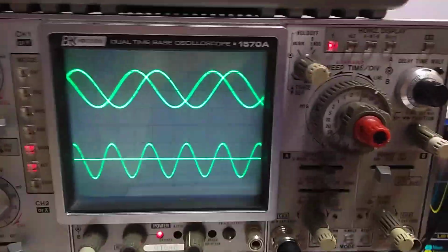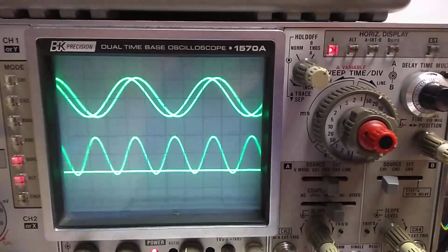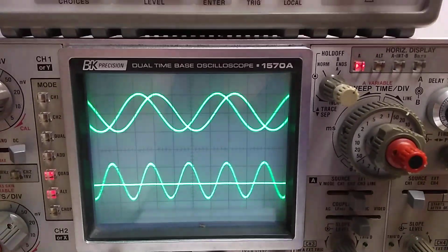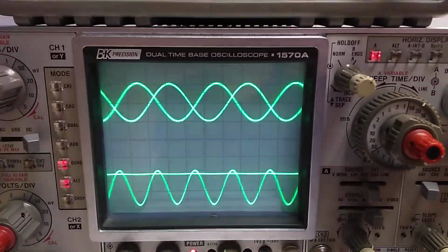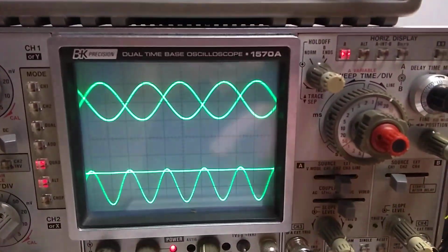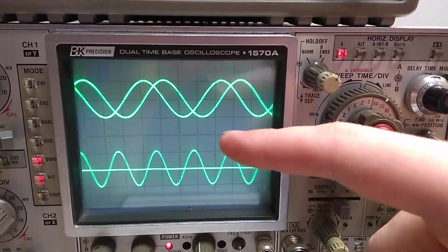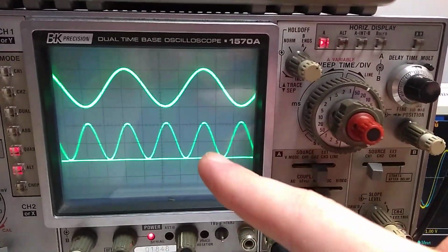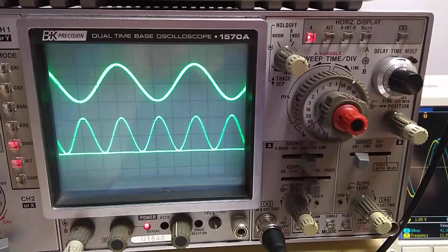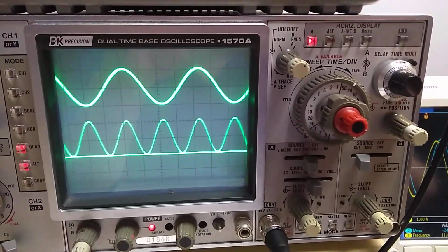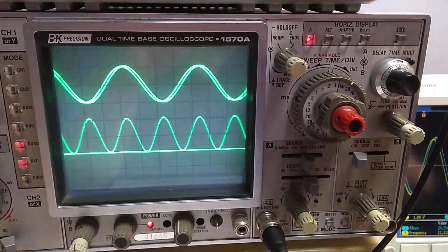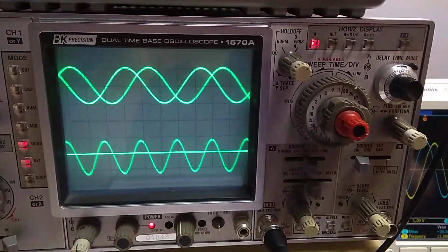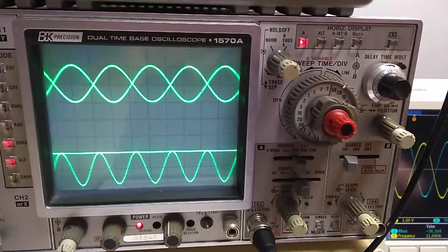And without even looking at the math, you should be able to guess the DC offset as a function of phase. Is it sine or is it cosine? Well, when the DC offset is at its maximum, the two sine waves are in phase. There's a 0-degree phase shift. So cosine of 0 degrees is equal to 1. And cosine of pi is equal to negative 1.